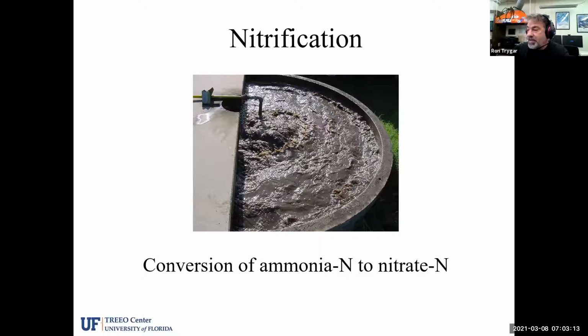And you can see here in this picture, I'm showing you an aeration tank. This is at a small package type treatment plant that uses round precast concrete tanks as their aeration tanks, with a single diffuser header or airline coming into the aeration tank. And this would be carrying oxygen with it. We know that air has about 21% by volume of oxygen.